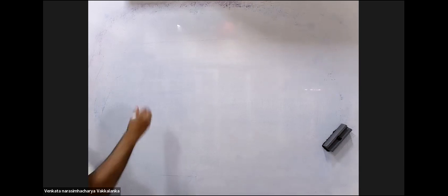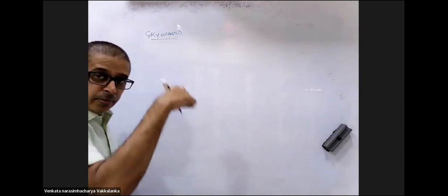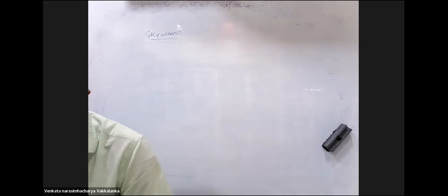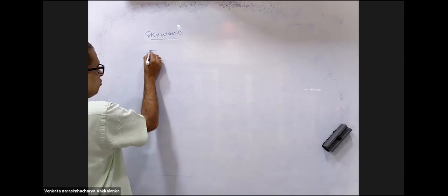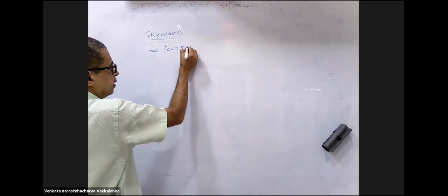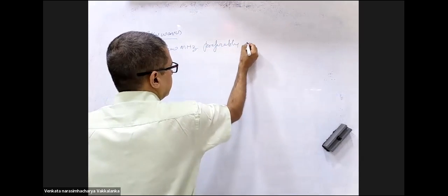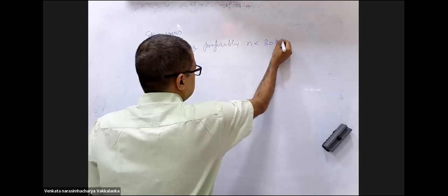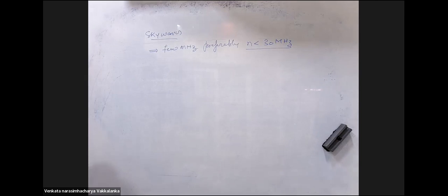No, listen. Sky waves. Many questions are coming on this; they are repeatedly asking questions on this. Firstly, sky waves, a few megahertz. First point: I can transmit signals of a few megahertz, preferably frequency less than 30 megahertz. Sky wave transmission can be done with a frequency lesser than 30 megahertz.